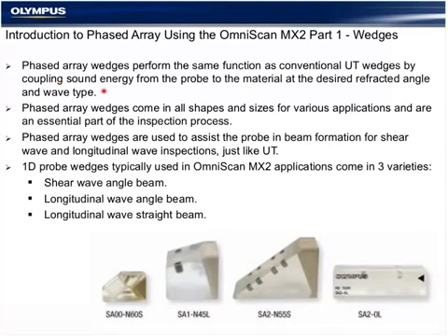They come in all shapes and sizes. They can be customized. They're specialized in the catalog for scanners or manual inspection. They generally can be divided into 3 specific groups in our catalog and in the applications. Shear wave angle beam inspection: in this case, we would steer the beam at a refracted natural angle of 55 degrees in carbon steel. So we would cut this wedge at approximately 36 degrees. The smaller the pitch of the probe, the greater the beam steering below and above 55 degrees.